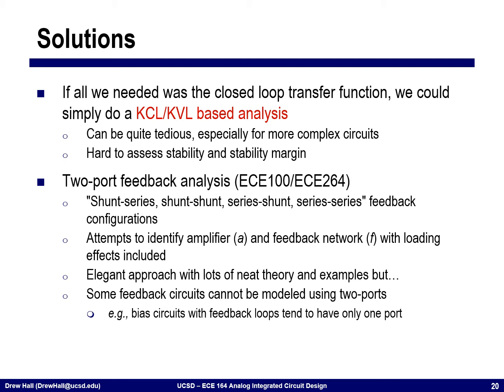Worse yet, and I think this is the biggest drawback of that type of technique, after I do all of that work, I do all of the node equations, I reduce this down to a nice closed form equation, I can't even assess the stability. I have the closed loop transfer function, but I can't prove that it's stable. Okay? If I really wanted to prove it's stable, now I need to go back and find the roots of 1 plus T, which I probably didn't formulate my expression in that kind of structure anyway.